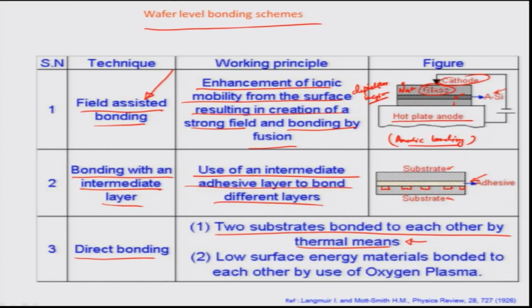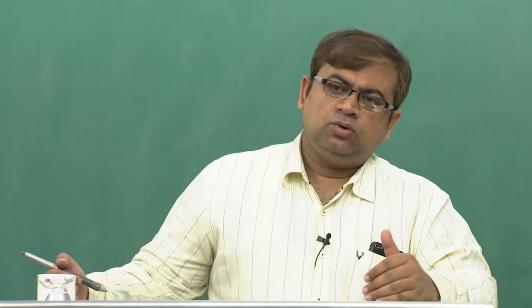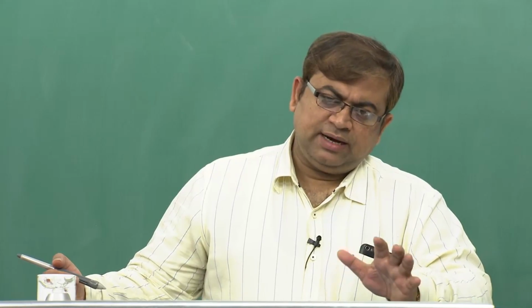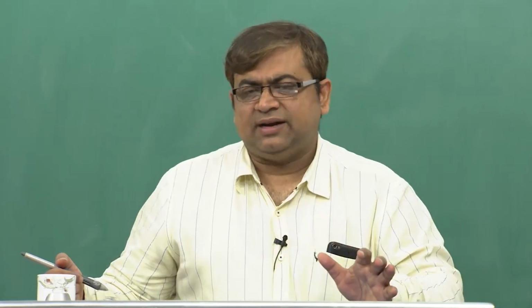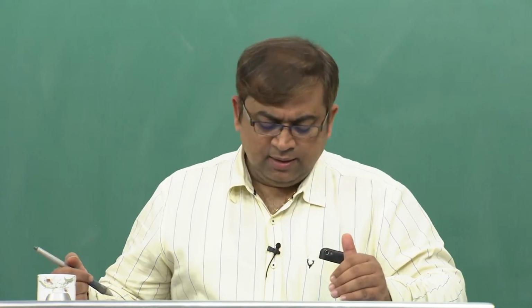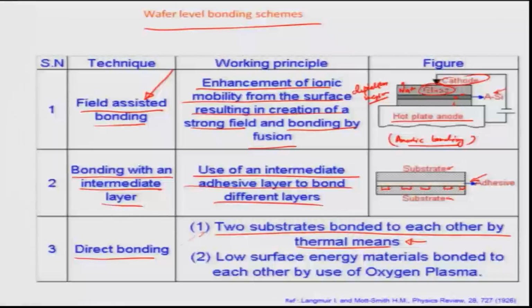But again, thermal processes are really not preferred to that extent, because thermal stresses are induced, which can cause warping or a change in the characteristics of the wafer, and there may not be good bondability between them because of that. So typically we try to avoid creating such defects in the structure we are working on, and therefore thermal bonding is not a very preferred means when we talk about microstructuring alone.